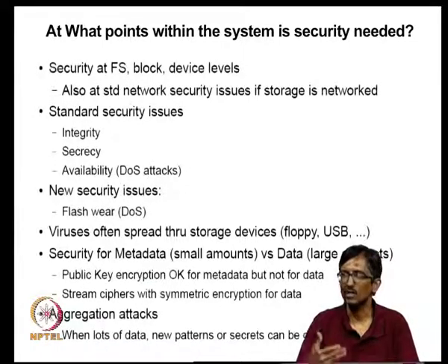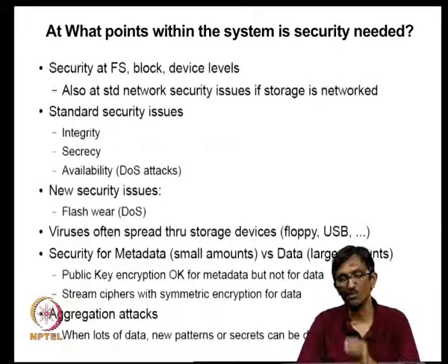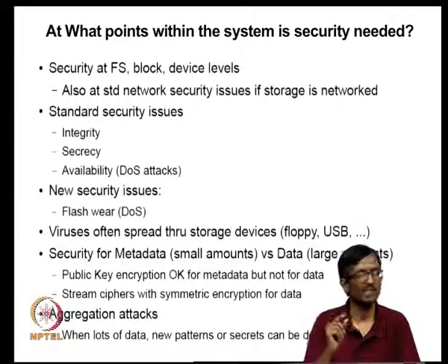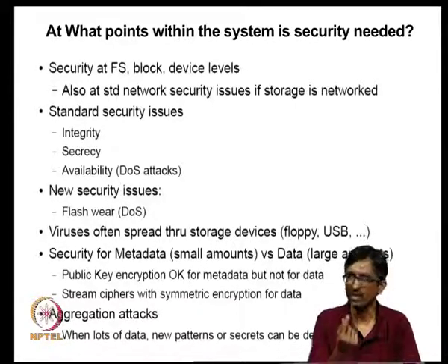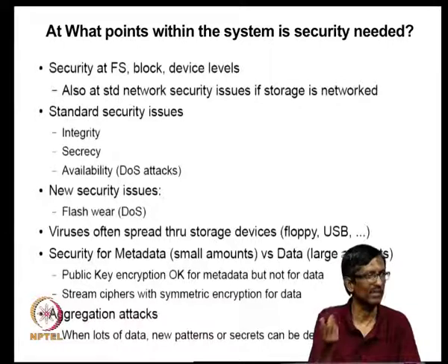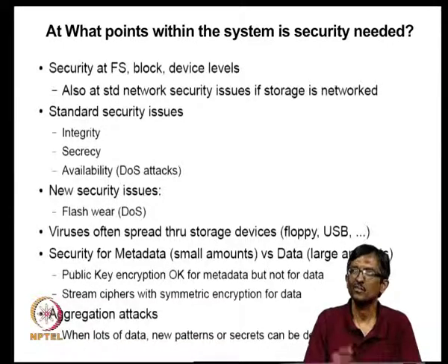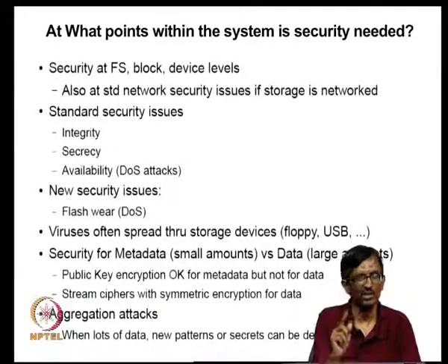This has happened also in other contexts. For example, in the 1960s, we had something called core memory. The core memory was basically a magnetic kind of thing, and it would have two states, 0 and 1. When some current is sent, it flips in one direction or the other. Now, somebody can write a small tight loop, basically branching to the same memory location and executing it repeatedly. That means the current is going through that coil all the time, and finally that particular coil element gets burnt out.